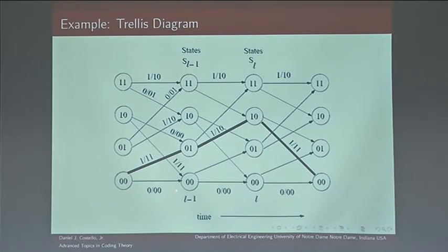And again, from the state 0, 0, we either stayed there or we went to the 0, 1 state, or the 1, 0 if we switch them, with 1, 1 outputs. And the other case we looked at is when we left here, we went either to this state or to this state with these outputs. And again, the branch labels here are just like we label them with the state diagram. The first bit is the input bit, then after the slash are the 2 output bits.